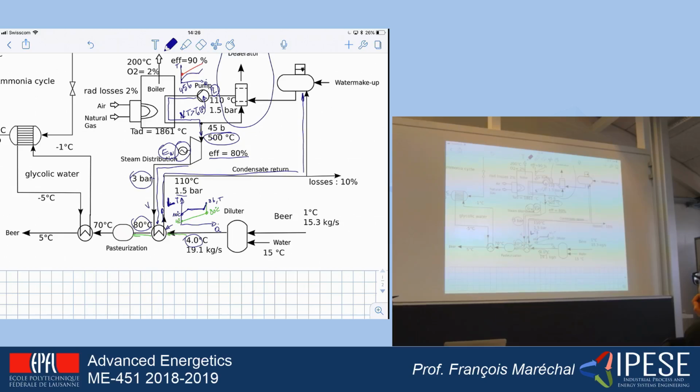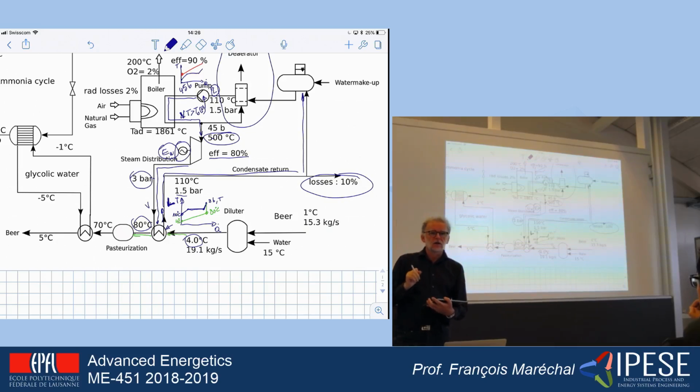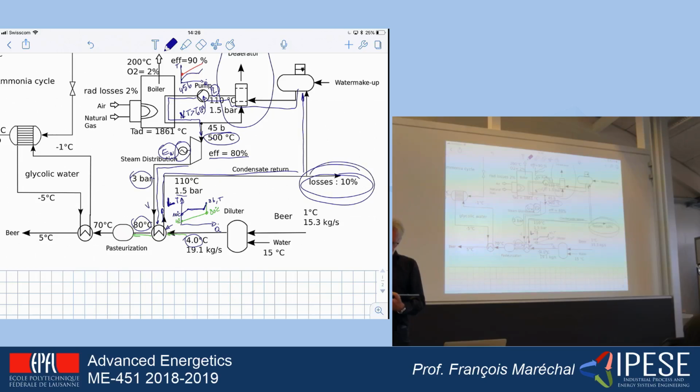It seems, however, that on the way back home, the water has been lost, and there are some losses, which are mainly losses that occur in pipes because the pipes are cooled down, and sometimes there is venting that is there to prevent having gas traveling with the liquid. Okay, so you have some losses, and the losses have to be compensated because the water has to go back here. Okay, and the amount that is lost here is going to be compensated by adding cold water here.